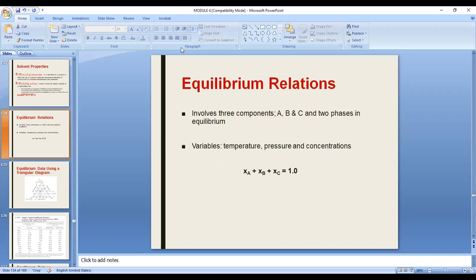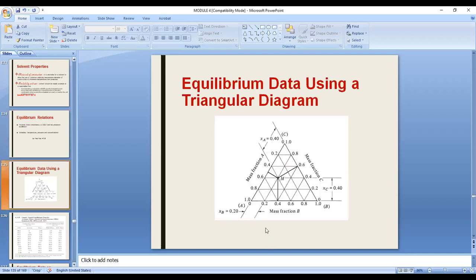Thankful for this one in the inbox. All right. Thank you for this, Joshua. Your A is your solute. Your C is the solvent, the one that is responsible for taking out the solute from the B, and B is the inert part of your feed. Oftentimes, it's your water. Okay, most of the time, it's just water. Okay, that's it. So, you are interested in A and C. You're not that interested with the inert part or the water. Okay, now, this is the equilibrium triangular diagram, something that is unique for extraction only.